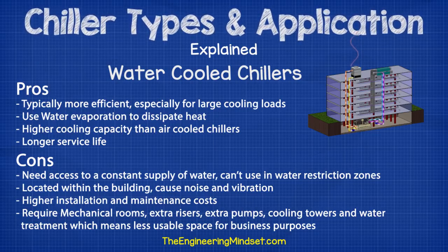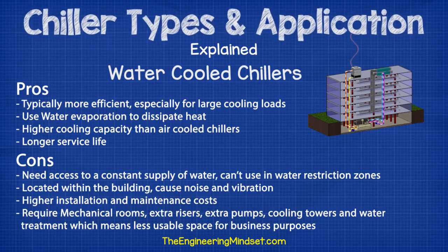Water also has a higher heat capacity than air, so it's inherently easier to remove the heat. Water-cooled chillers can also handle larger loads for the floor space that they consume within the building, and water-cooled chillers generally last longer because they are held within the building, so they're going to deteriorate much slower.